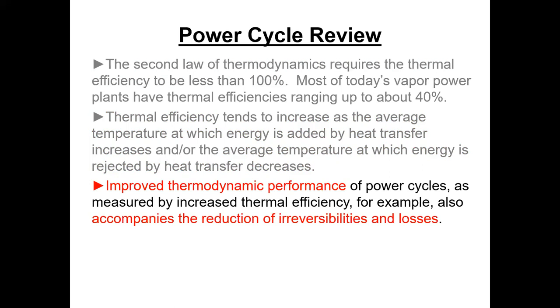If we could decrease the pressure drop through the piping, perhaps we put in a larger diameter, but of course, this would have to be designed in on the front end, and the design engineer has to decide what diameter pipes he's going to put in.